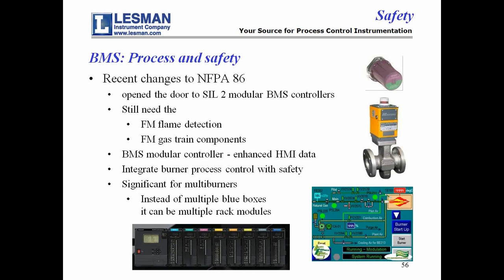A step even beyond this is safety instrumented systems, widely used in the chemical process industries. Again, insurance and liability is the driving force behind this. And they got the ISA and the IEC standards to cover how you analyze it, what you do for designing, and how you actually come about with factors that tell you what you're going to need in order to minimize your risk. And a lot of people have probably heard about SIL certifications. The higher the SIL certification, or the SIL level actually, the greater the impact of failure and the lower the failure rate that's acceptable.